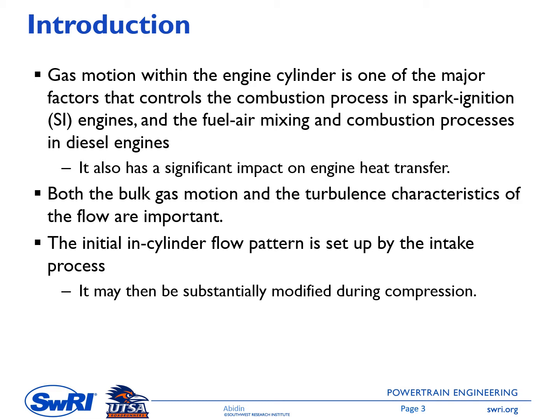Some of this bulk flow will break into fluctuation flow, into turbulent flow, close to the end of the compression stroke, and this turbulence will enhance the combustion process. And then the bulk flow that is close to the wall will increase the heat transfer coefficient and thus increase the engine heat transfer.